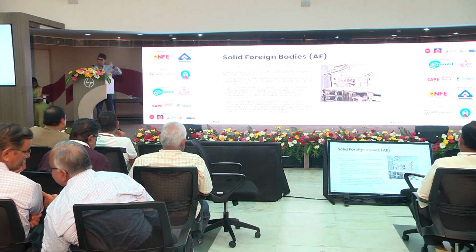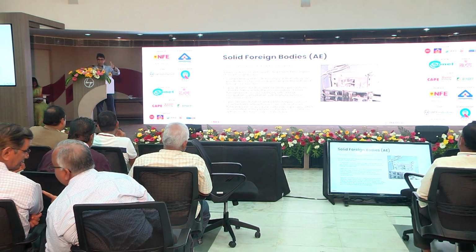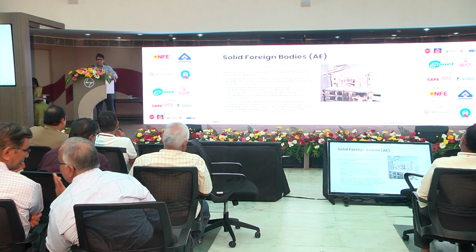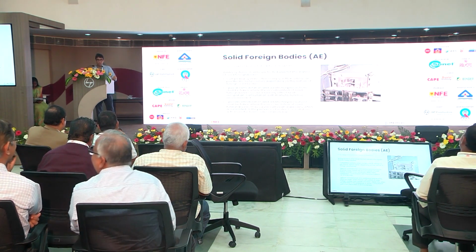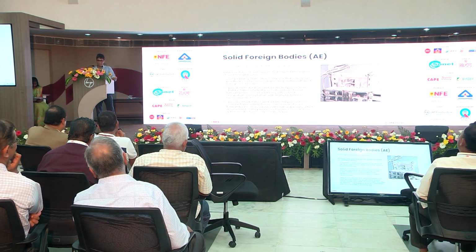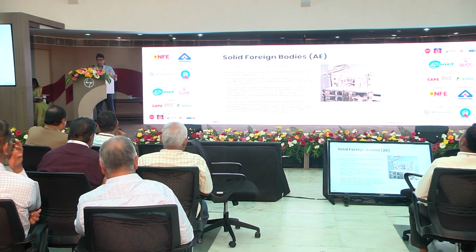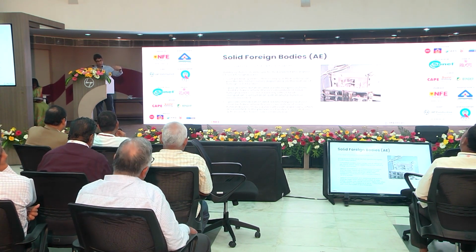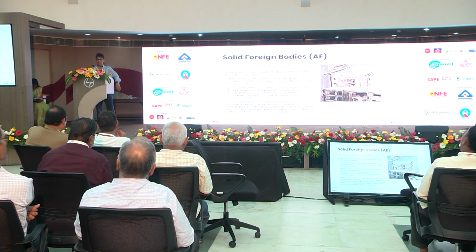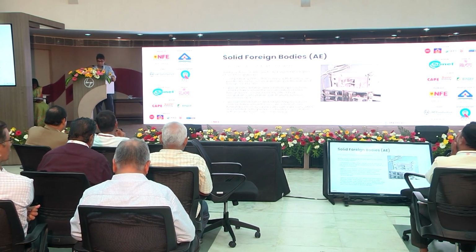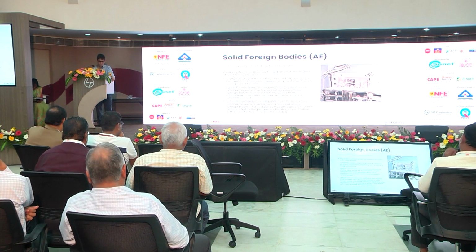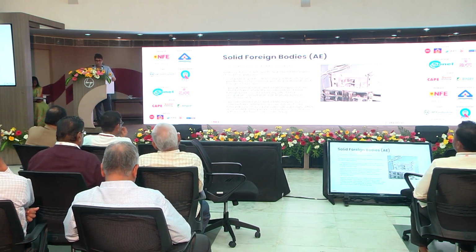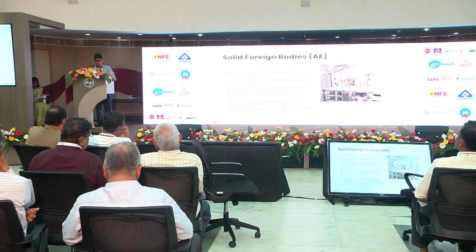Say you have a vent, and the dust accumulates in the vent of the panel. As yesterday, a gentleman spoke about panels overheating. So if the dust is going to accumulate in the vent, you must make sure that this dust does not affect the heat dissipation characteristics. So again, this is a good idea to consult with your manufacturers for this. A lot of manufacturers for good panels will gladly help you with this.